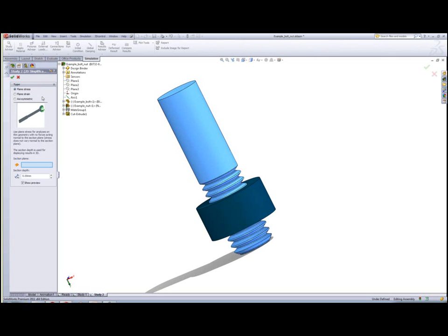And the one we're going to be working with this morning is the axis symmetric option. Now this enables us to simulate geometries, material properties, loads, and fixtures that are symmetric about an axis, in this case about this natural axis of that shank for the bolt.